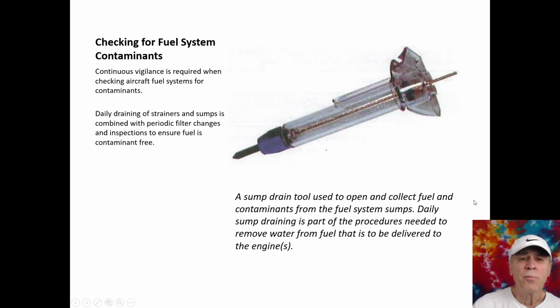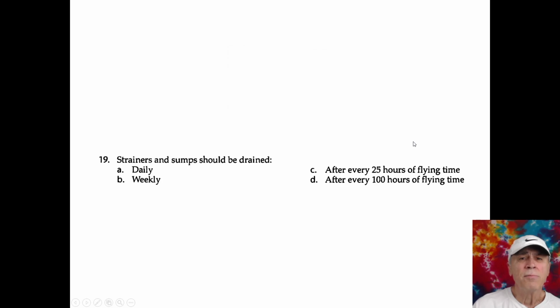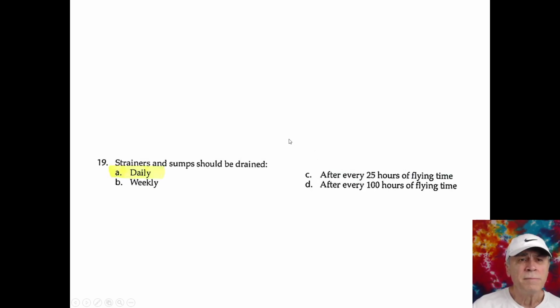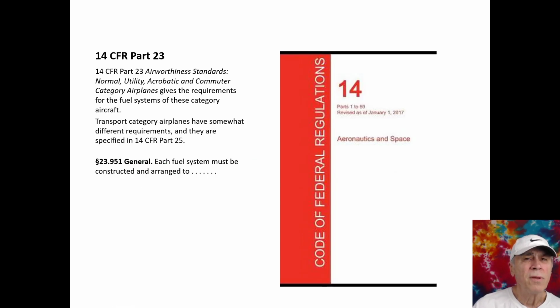Daily sump draining is part of the procedures. All right, this is something pilots do. Yes, they do that daily. That's one of the first things the pilots do. They pull out the sample, they bring it into the hangar, they dump it into our fuel dump, and they do that daily. I'm mostly looking for any little bit of water that it's accumulated. So daily. Sorry, I didn't quite understand the question at first.